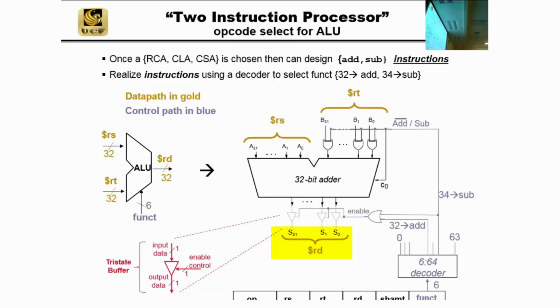They interfere with each other. So in other words, this is a bundle of wires. How many wires? 32 in MIPS. This was 32, and this is 32. But let's just look at the least significant bit. If I zoom inside here, which is what I'm doing in that diagram, there is the output, let's just call it sum 0, and then sum 1 line, and so forth.